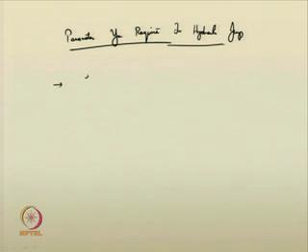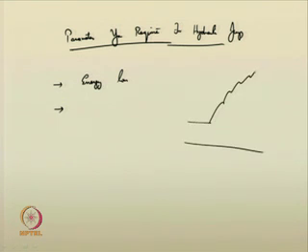Say, energy loss as a parameter. You can also associate the energy at this location upstream and the energy at this location downstream; whatever change in energy is there, that is the energy loss. If you are designing a hydraulic jump based on energy loss, then energy loss becomes a parameter.